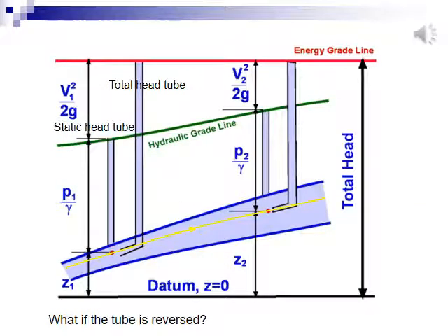The picture here shows the geometric meaning of Bernoulli's equation. We can say this is a graphical illustration of Bernoulli's equation. Here's a tube flow running to the right. In the flow, we pick a streamline, the yellow curve in the picture. At point 1 and point 2 on the streamline, we put piezometric head tubes and total head tubes respectively. Pay attention that the two tubes should be installed very closely to ensure they give values for the same point.